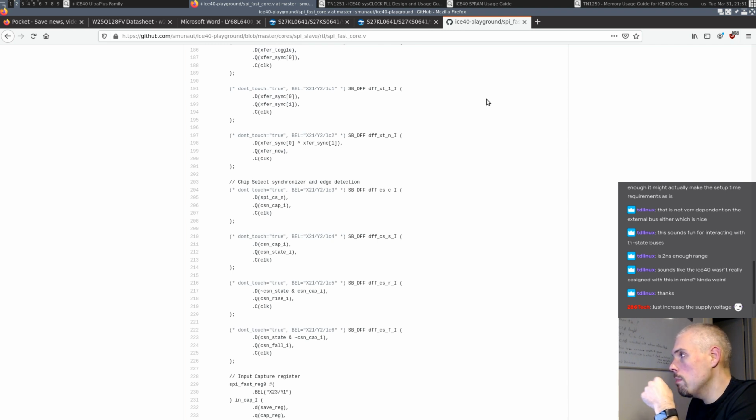So the question was, why did I have to do that? Well, there are two reasons. The first is I'm crossing clock domains, right? Because I'm passing data from the SPI clock domain to my system clock domain. And currently NextPNR does not allow a user to constrain cross clock domain path. It will analyze the delay and tell you the delay, but it can't guarantee anything, and it won't check or try to make them as short as possible or any of that stuff.